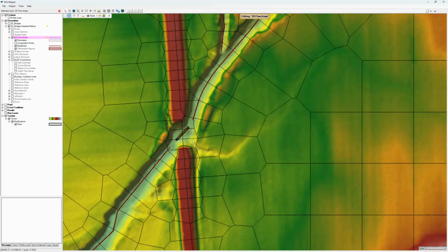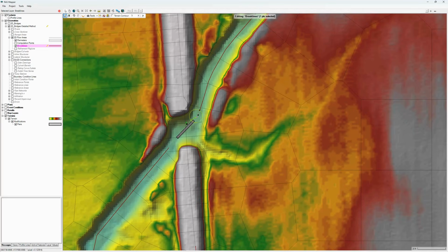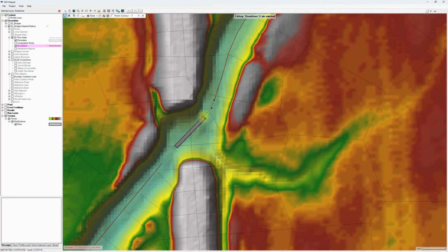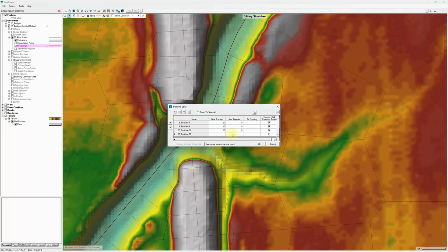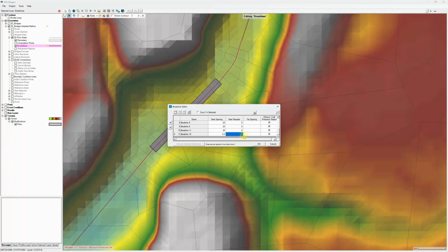One tricky part of this method is that the pier placement needs to line up well with the cell faces and should not create leakage across the mesh. So the mesh around the pier has to be adjusted carefully. This is usually where break lines or local refinement regions become useful. HEC's bridge guidance recommends aligning the structure with cell faces.